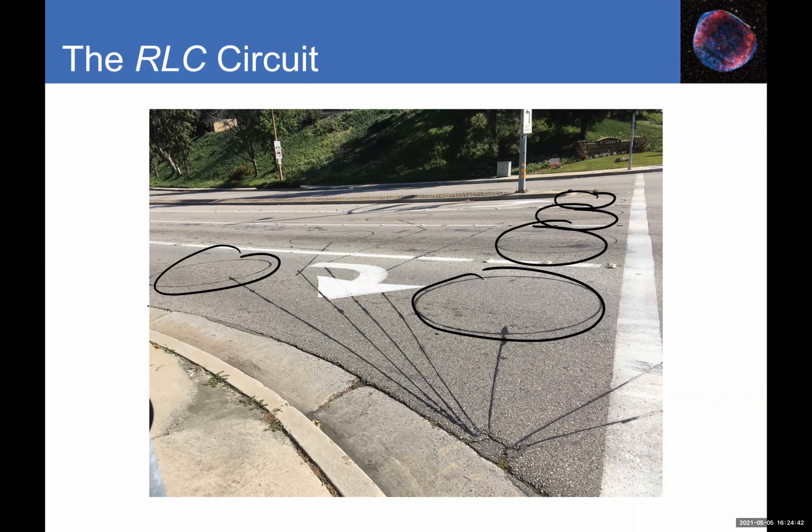So the change in inductance L of the loop changes its natural frequency of oscillations. Then the control electronics connected to those coils detect the change, and a signal is sent to the traffic light, which changes from red to green. Every time you approach a traffic light, especially at night, and it right away changes to green, hopefully now you understand why, and maybe you can even look and see those coils.